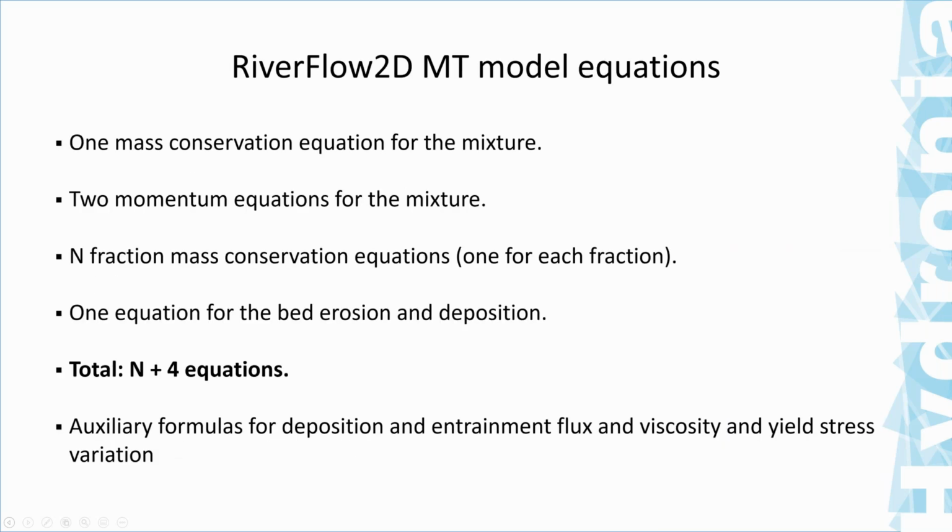Okay, so in terms of the model equations, we have many more equations than we used to have in the original MD module that considered only constant properties. Now we have one mass conservation for the mixture of sediment and water. We have two momentum equations for the mixture.